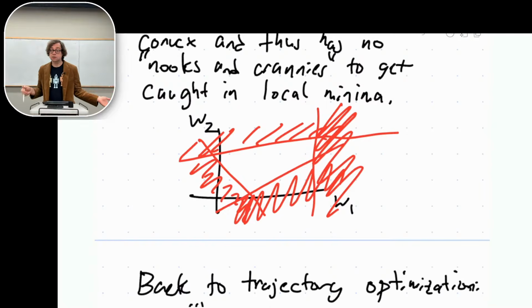Yeah, it could be blazingly fast. Yes, it could be a really fast optimization because you could use a local solver and it will get you right down to the minimum. Of course, it also depends upon the cost function. But who gets to choose the cost function? We do. We could choose a linear cost function, or a quadratic cost function if we thought it was good, and then all of a sudden, it's a quadratic program or a linear program. And it should solve very quickly.